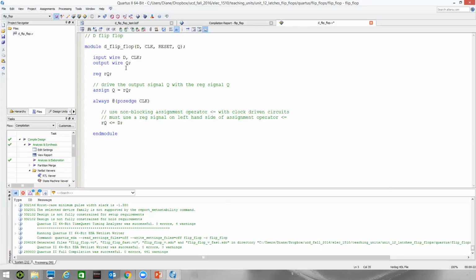That's what I call them all the time. So reset is another input here. All caps, kind of as it looks like I'm yelling. I'm not. So now I can have positive edge clock, and I'm going to have neg edge. I'm just using neg edge because I'm going to implement this with the Altera, and it works really well with the buttons. So neg edge reset.